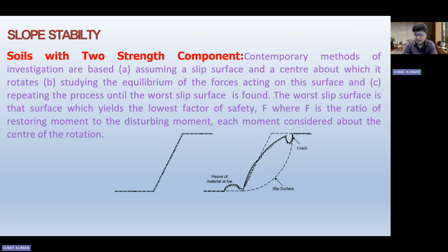The shear stress applied at that specific section up to 99 kPa doesn't move it in any direction. But if the stress increases so that it reaches 100, it is on the verge of failure, or if it crosses 100, that is 100.1 kPa, then the failure takes place.